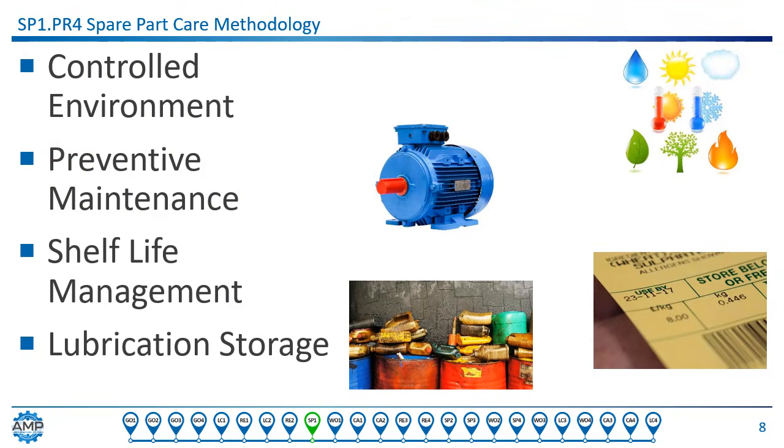Part storage is spare part care. There's a little bit more to spare part management than just being able to find parts or protect them from getting ripped off by people. Some parts require care while being stored. Some parts have a shelf life that needs to be honored. Others need special storage environments like freezing or being kept warm. And then you have to think about chemical properties and flammability. These considerations all need to be defined and controlled as part of the spare part management program.